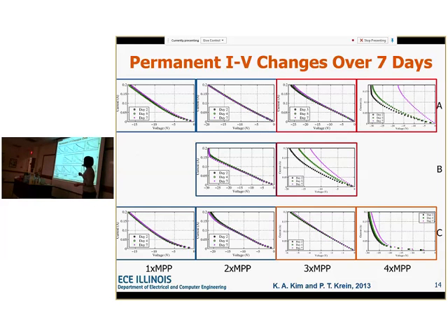These, although these were the ones that did go into second breakdown, this one, the A3, has a small amount of change, but these ones have a really clear change in the reverse bias characteristics. And I'm only including 3 days, but the trends did follow that. So we're seeing a really clear change in the reverse characteristics of the ones that went into second breakdown. So this leads me to believe that second breakdown, if it goes into that stage, you're actually doing damage to the cell itself. And that's really the threshold that we want to avoid going into.